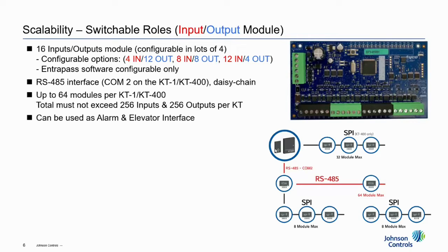And in terms of the wiring, it's RS485 interface. It's a 4-wire RS485. Okay, meaning that from one of the module, you basically just extend the wiring over to the next module. And that's where you can expand the module without the need to incur heavily on wiring.